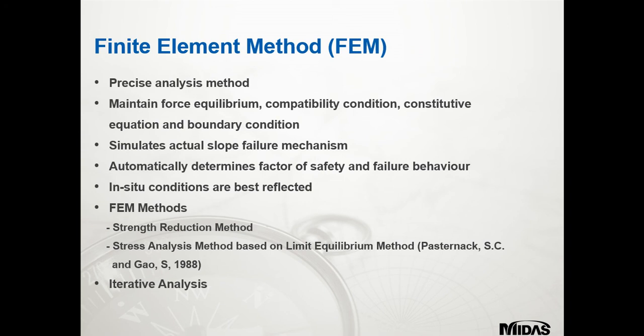Excuse me. So just moving on to the finite element method, or FEM. Finite element is a precise method for analysing slope stability, as we don't need to make assumptions for failure surfaces. In finite element for the model domain, force equilibrium, node compatibility conditions, constitutive equations for ground material and boundary conditions along model edges are satisfied.